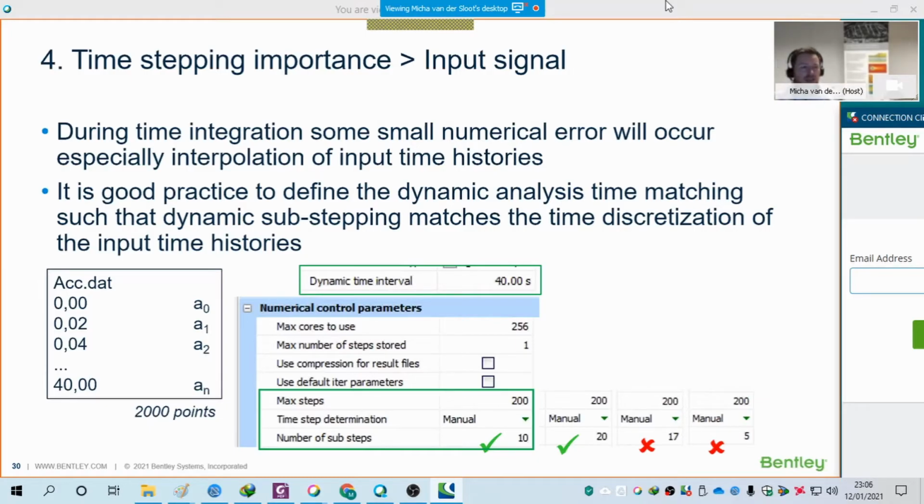I've not seen anything like that in all my time looking at these models, but I think it's a very fair question, and also that's something that indeed you should consider: have the earthquake motion coming in as upward motion, and then have a viscous boundary at the top to absorb the energy there.